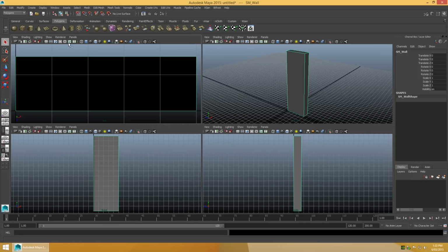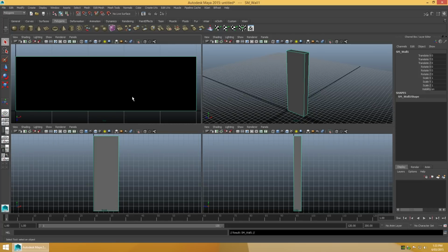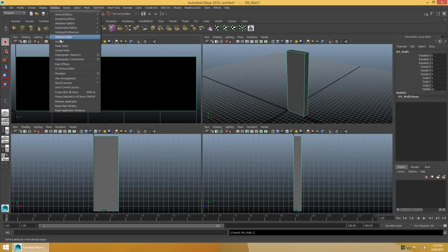As a bonus, I thought it may be beneficial to demonstrate the procedure for adding a collision mesh within Maya. Although the Unreal Engine has the functionality to generate collision meshes, it can be a quicker process in Maya depending on the complexity of the mesh. It's as simple as duplicating the original mesh and then renaming the duplicate with a prefix of UCX_.